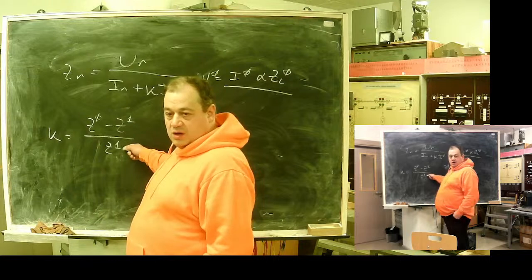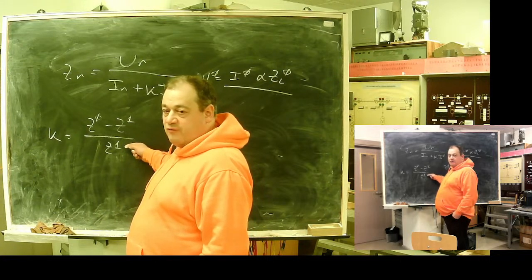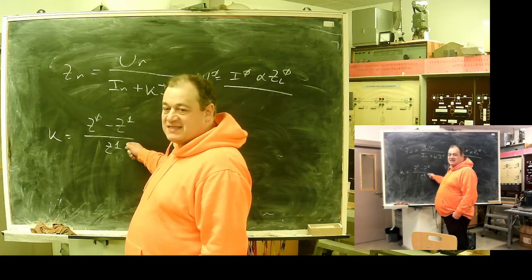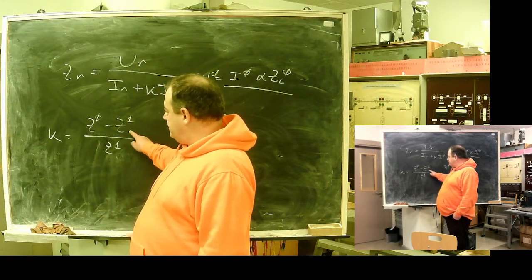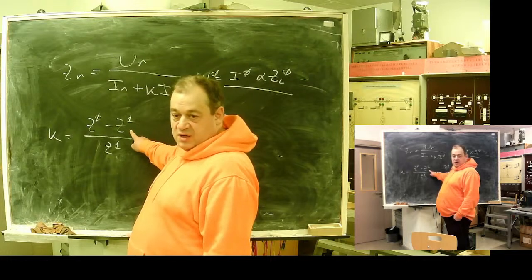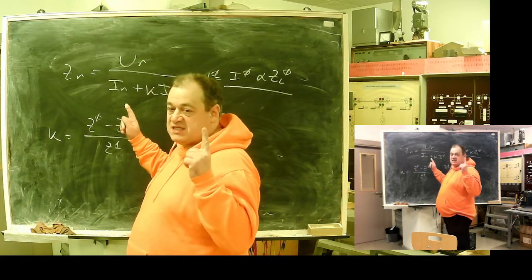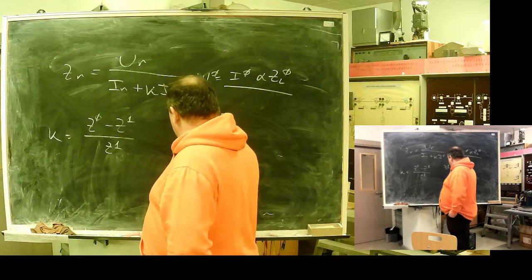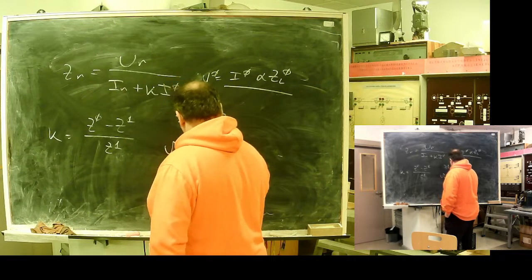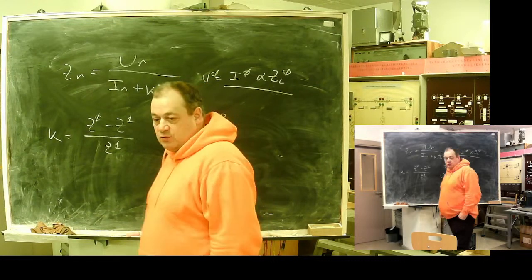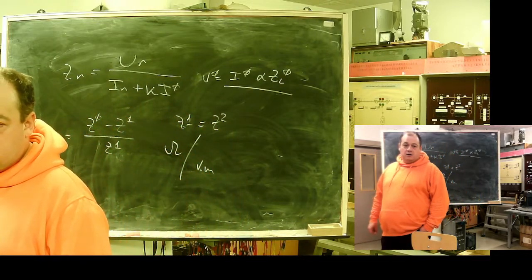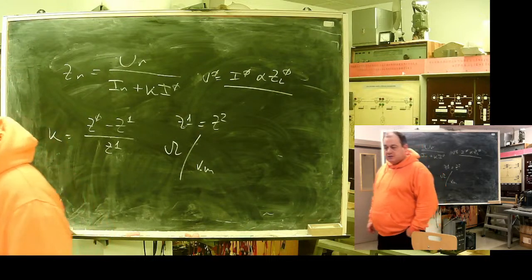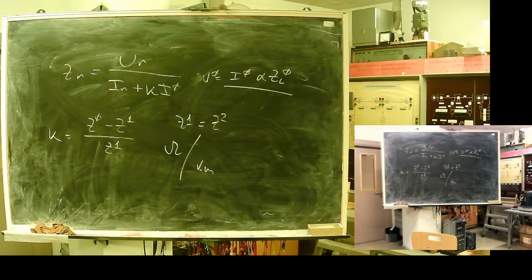What are these? Either full line resistance, or resistance per length unit. These values are either full resistance of the line, or ohm per length unit, per kilometer, per meter, per mile. Don't make a mistake. Okay.